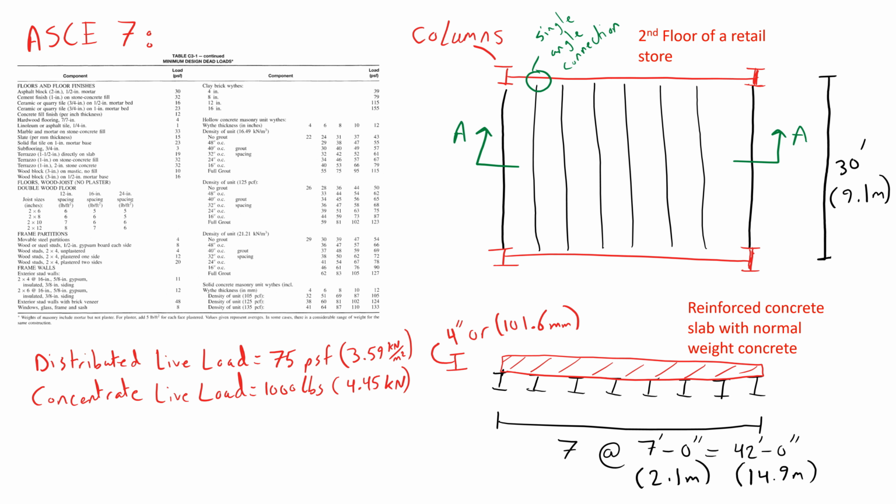The load caused by the concrete slab per unit thickness is given as 12 pounds per square foot. Weight of concrete with reinforcement can be calculated using the density of the concrete and the weight of the used steel reinforcing bars instead of using the table for a more accurate assessment of the load. The movable steel partitions have an approximate uniformly distributed load of 4 pounds per square foot each.